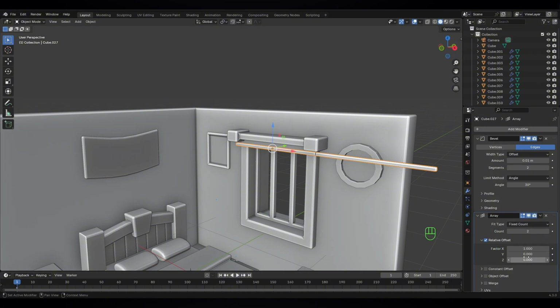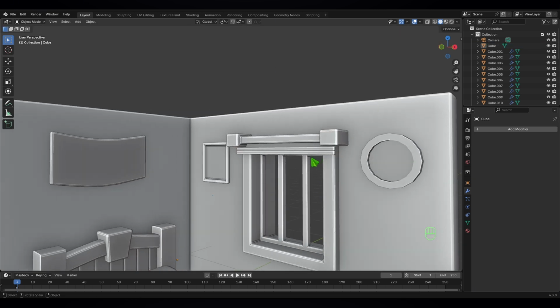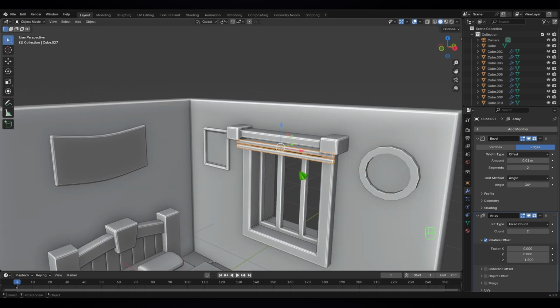And I want to make it Z-axis 1 and X-axis 0. And let's put -1 because I want it to go down. Okay, just select it and let's put 5. This is going to work. And let's go to camera view.